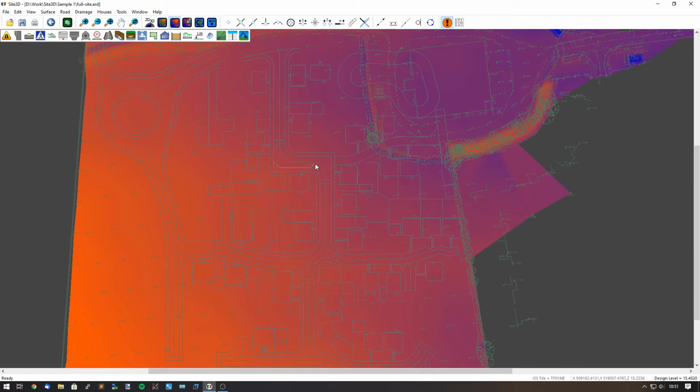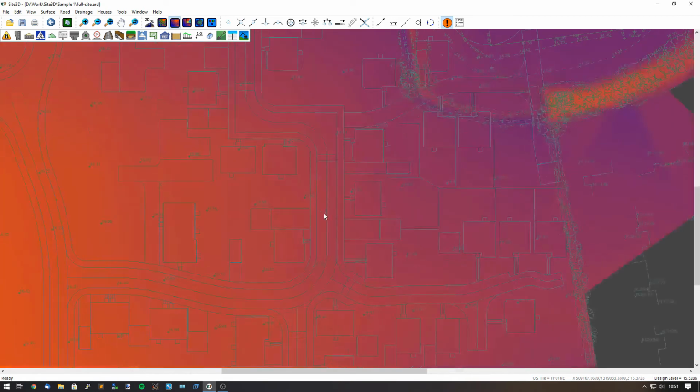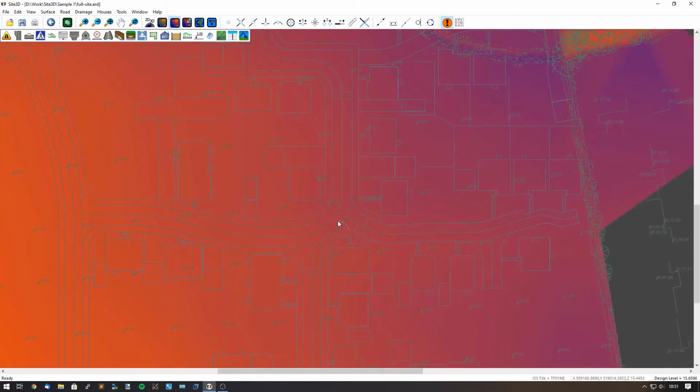So anywhere on the road, the water is going to rapidly go straight across to the channel line, and then it goes along the channel, which is great. That would suggest that we're not going to have any kind of ponding, or puddling I should say, on the road surface. It's going to go straight to the kerb and into a gully, which is great.